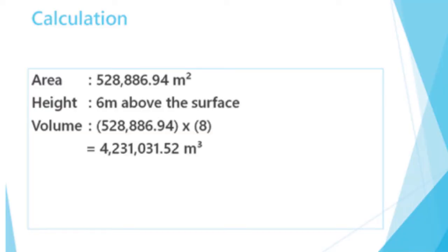Before we did a calculation of the volume of the area that we need to reclaim, we decided the specification of the land reclamation, which consists of development phase, slope, formation level and fill material. To calculate the volume, we simply need to find the area using Google Earth and multiply it with the height.